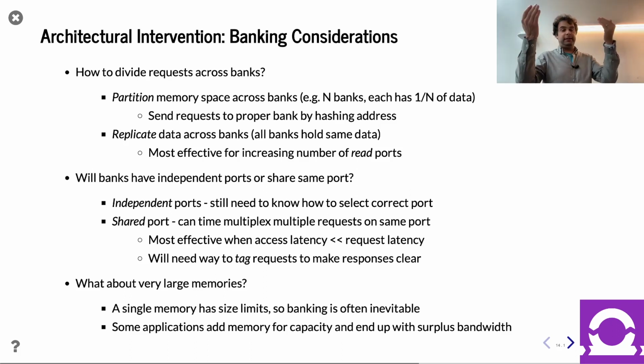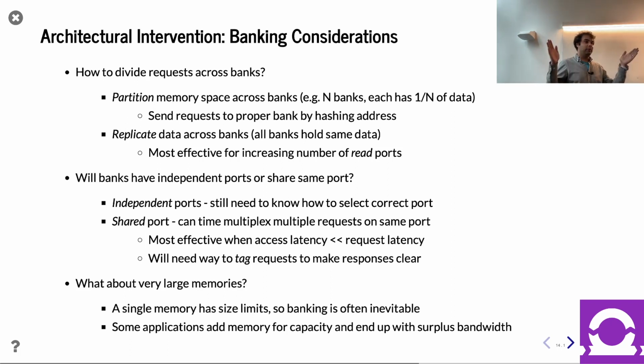And you can imagine, architecturally, you can almost guarantee this works out really well sometimes. Let's say you're building SRAM for instruction fetch. If you have a 2 wide processor, you're going to grab PC and PC plus 4 every cycle. So guess what? If you have 2 banks that are interleaved every 4 bytes, you can use both banks every cycle, for example. Or maybe you want to use 1 bank one cycle, 1 bank next cycle, in which case each bank would be 8 bytes wide or something.